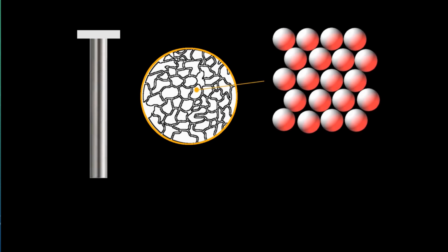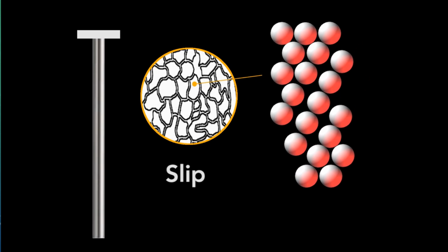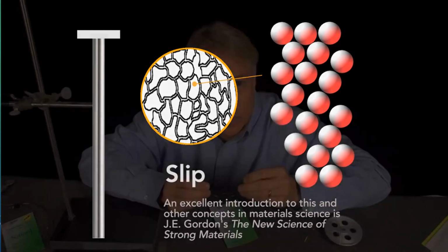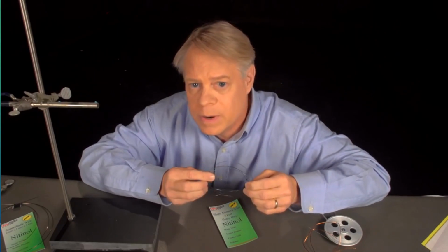Metal bonds can be formed more easily than in nonmetals, so the atoms slip. Although it's a bit more complicated than implied here, which looks like spherical atoms rolling along each other. It involves defects in the crystal that allow the atoms to move only small amounts. In nitinol, though, generally the atoms don't slip. They accommodate the stresses from bending, stretching, compression, and so on in a different way, which produces the memory effect.